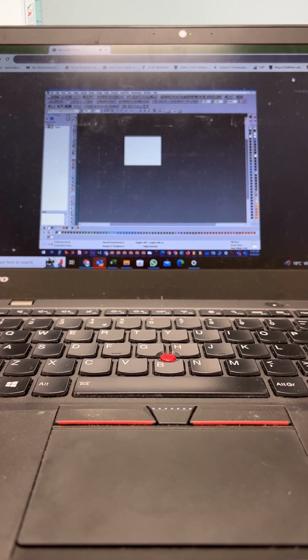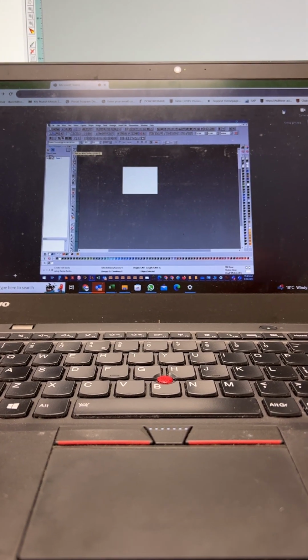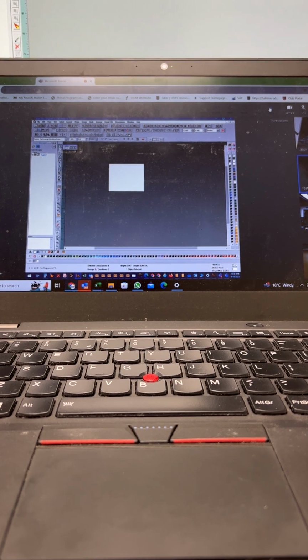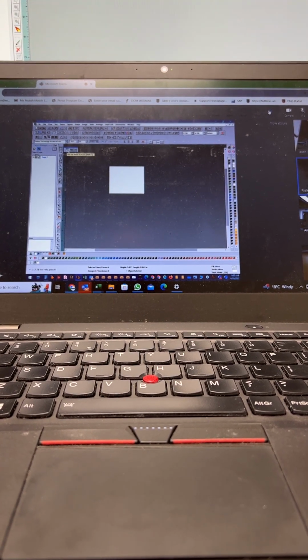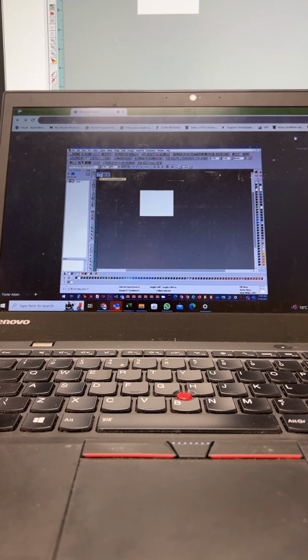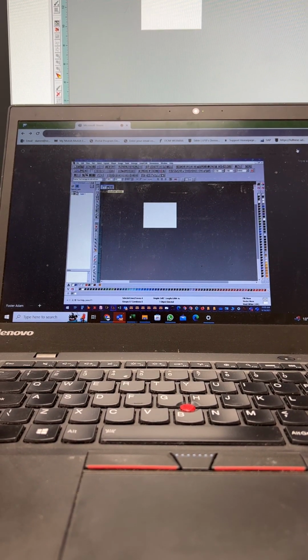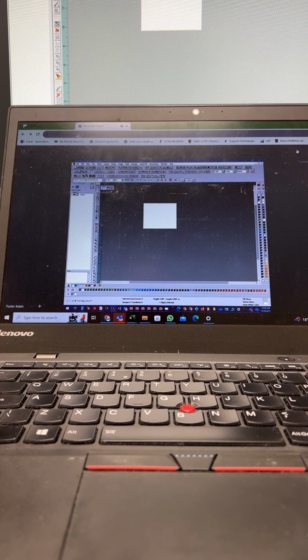One is you can click on this letter T. That's your text tool. If you click and hold down the mouse, there'll be a secondary toolbar. The capital T is the text on the work surface so that you can see it as you're doing it. Text entry is a dialog box where you see just regular text, and then you select the font style and it shows you once you've left the dialog box.